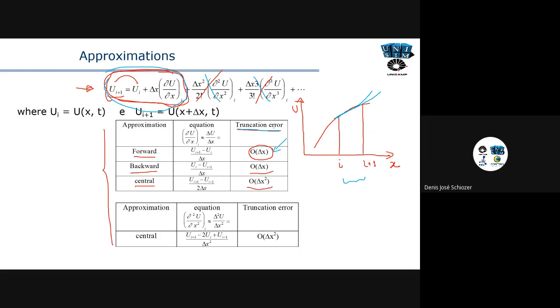We normally put this truncation error together in a category we call numerical approximations, okay? So when I'm solving the equations using these finite element methods, approximating the solution, linearizing the equation and solving it this way, we have these errors that we call numerical errors. There is a lot of information about this in books and papers, and I'm going to go through it very briefly. The most important part is for you to consider that in our area the size of the grid block is large, so these numerical errors are very significant, okay?